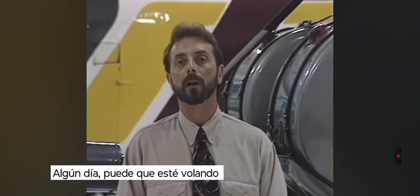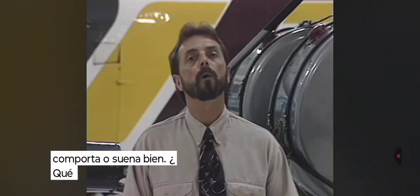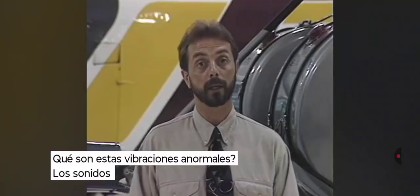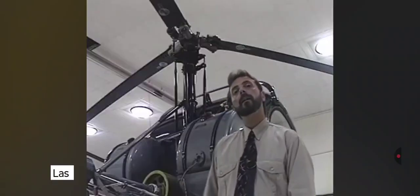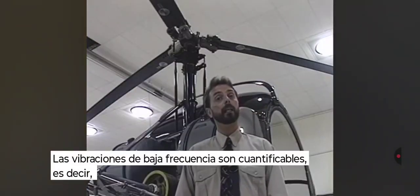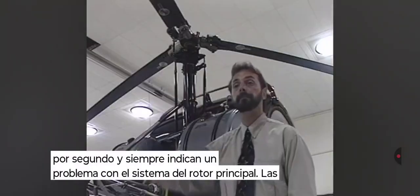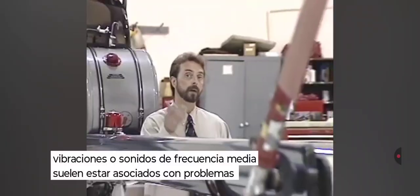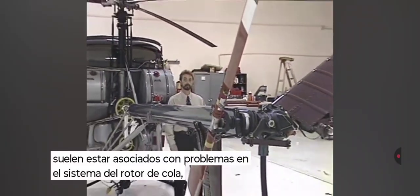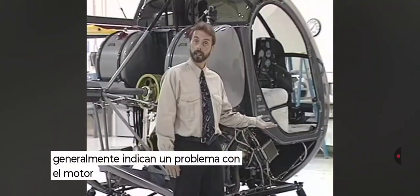Someday you may be flying along and notice that the helicopter just doesn't feel or sound right. Knowing what these abnormal vibrations and sounds could mean could give you a good clue as to what's wrong with your rotorcraft. Low-frequency vibrations are countable. That is, they're in the 100 to 400 cycles per second range and always indicate a problem with the main rotor system. Medium-frequency vibrations or sounds are usually associated with problems in the tail rotor system. And high-frequency sounds or vibrations typically mean there's a problem with the engine or the transmission.